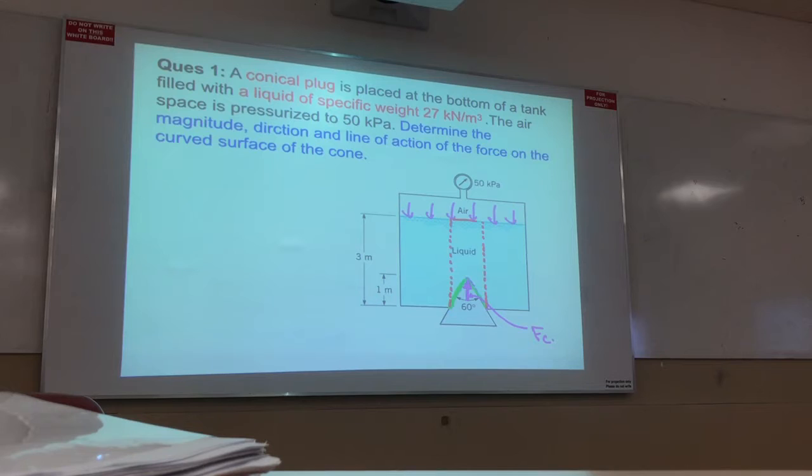So at the area, what is the force? The force given by air pressure is equivalent to the pressure of air times the area from here to here. Correct? This is the force given by air. I have to calculate this area. We assume this is a cylindrical shape, so the diameter of this portion is D. If I draw a line, this is D, correct?